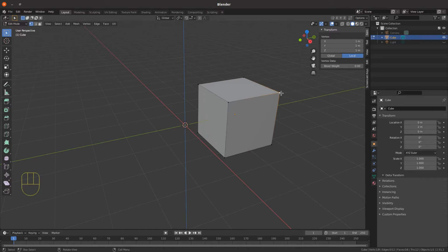That's because the dimensions, when you're working in edit mode, are referencing the object origin. So that's why I stressed about the object origin and the world origin in the object mode video. So video 4, I think, was the video that went on about Cartesian coordinates, and that's just to show you it's exactly the same Cartesian coordinate system, but now it's referencing the object origin.